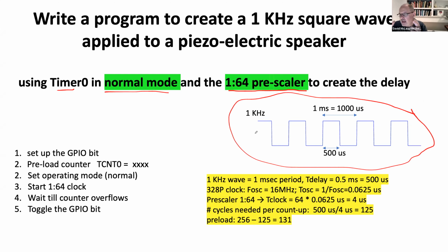Now, a sine wave sounds better than a square wave, and the reason is that if you listen to a sine wave, you'll hear a pure monochromatic waveform. If you listen to a square wave, it actually has something called harmonics in it. So this square wave will sound like a dirty 1 kilohertz tone because it has various odd harmonics associated with it, but that's okay.